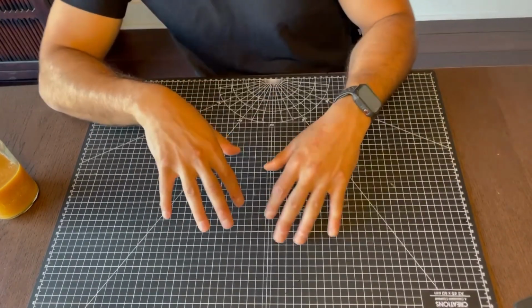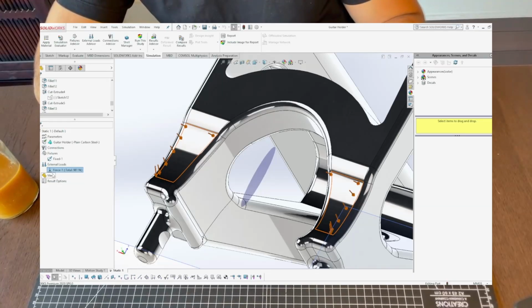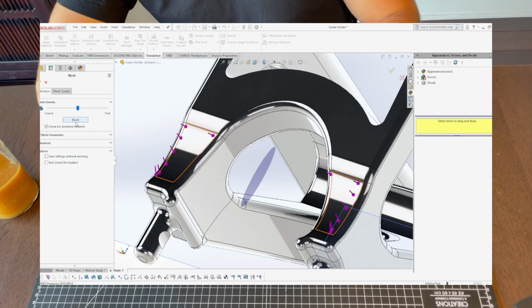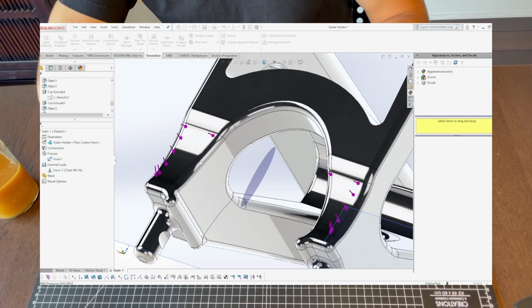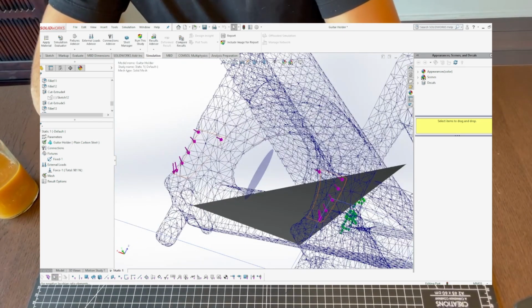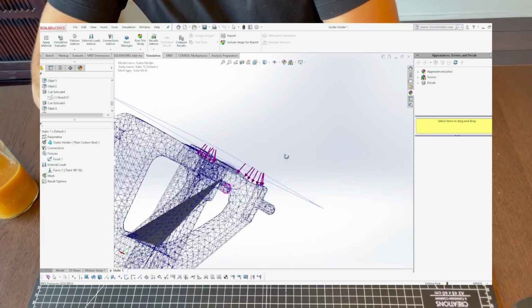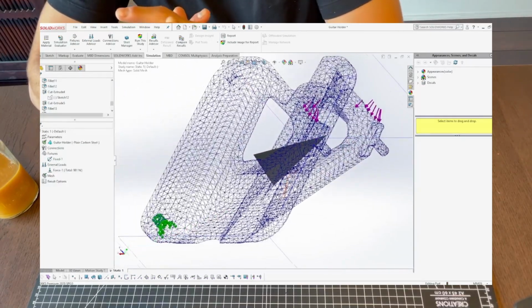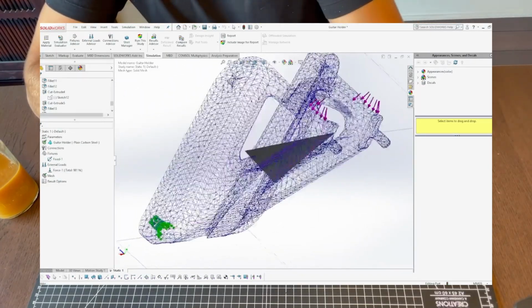After that, I picked the mesh size, and the mesh size, this is a very important term. It's one of the most important terms with, I think, finite element analysis in general. Remember the Legos from before? The mesh size is what defines how small these small Lego cubes are. And I talked about the trade-off. So in this case, this is the real-life definition of it.